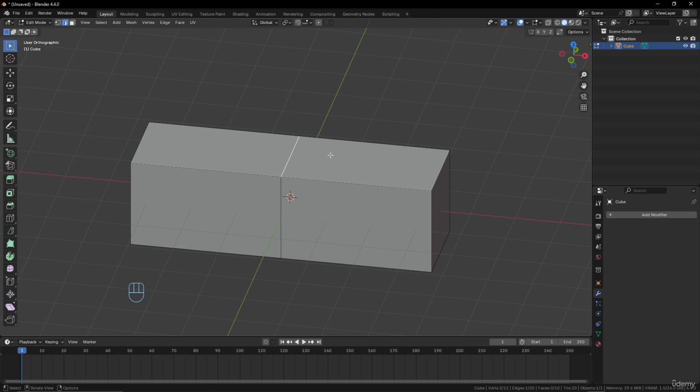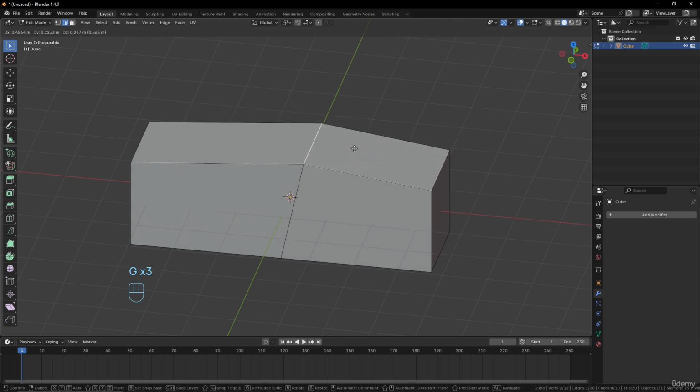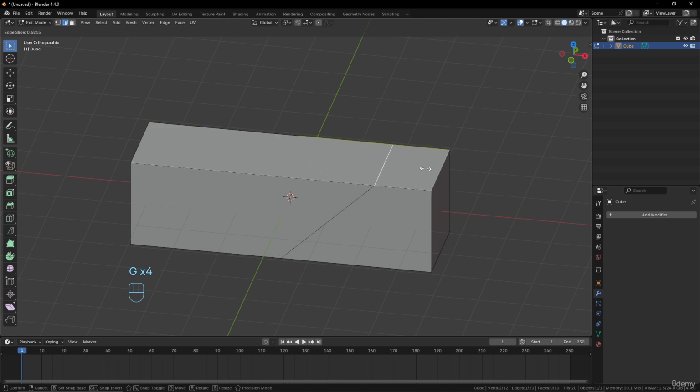So what I will do, I will use G and G again. You can see that G moves freely, and if I use G again, it will slide the geometry. So yeah, again, that one is not really interesting because just with the shortcut GG you will have it directly. And again, this one works with vertices, GG, okay, and not that one. So you have vertex slide and edge slide just with GG. It will work whatever you have selected, even an entire loop, GG, and you will slide your geometry like that. So yeah, can be useful sometimes, actually.